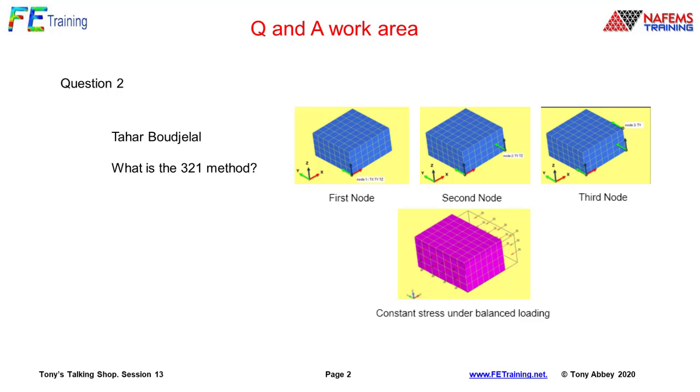The analogy is rather like what we call a minimum jigging method. If you're building something up in a jig, let's say you've got a hard, stiff jig in the factory floor, you start to either weld or fabricate something in that jig. And what you can do is you can be putting strains into the assembly. So when you take that component out of the jig, it springs on you.